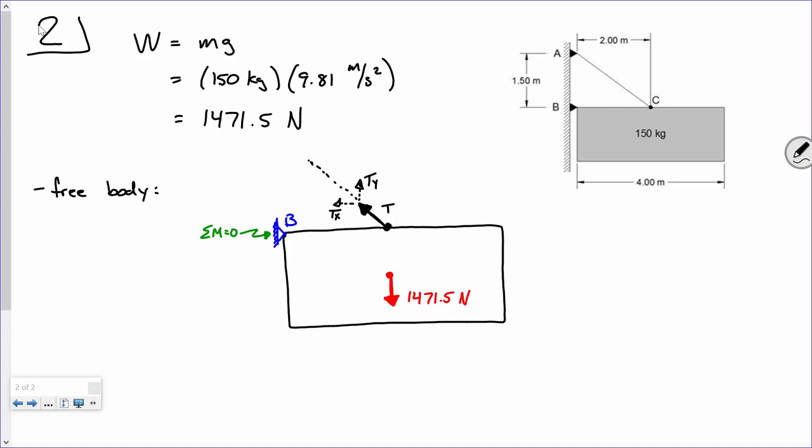One of the big secrets behind how to do statics problems really easily is what's called the principle of transmissibility. And I know that's a really, really big word, but it's a big word for a really simple concept. Let's say you and I are holding a rope, okay? And we're pulling 20 pounds, right? So you're pulling 20 pounds and I'm pulling 20 pounds, right? We're sitting still, tug of war, right? Neglecting how much the rope sags, does it really matter if you and I are here or if I'm all the way over here? We're still pulling 20 pounds.